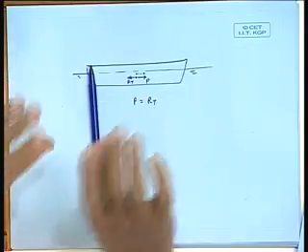So, this method is more or less okay, but one has to use one's own perception of the resistance force, how it is acting for other cases, particularly high speed vessels, when we are going beyond 0.3 and the pressure forces do cause a trim, how the tow hook position should be for applying the tow pull. Do I make myself clear? So, this point is very important and we have to keep it in mind.